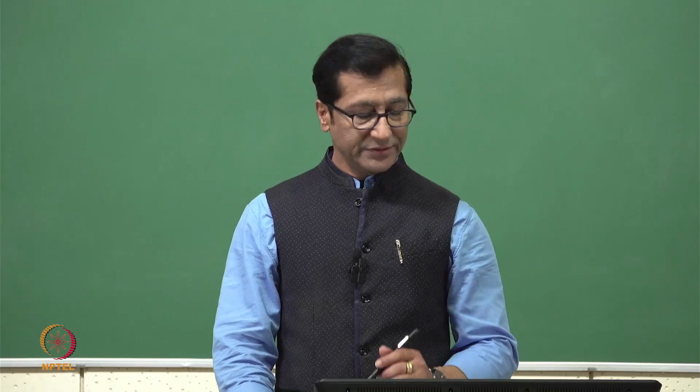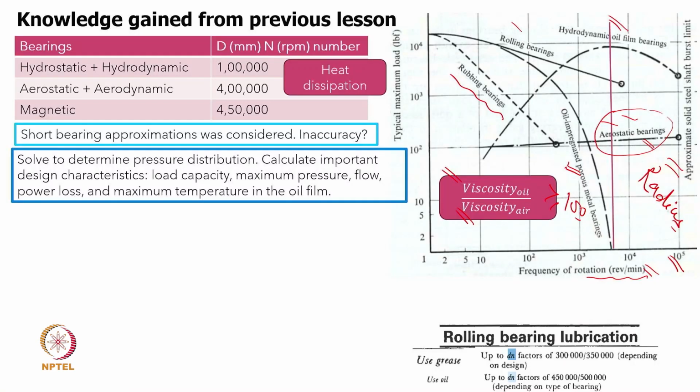Now, what has been learned from here is that many times a bearing is selected, and in this case particularly we have not defined a radius. So ideally we should use the term DN. DN is the diameter, that means the diameter of the shaft journal, times N, the RPM. So we consider the dimension and also the rotational speed, or basically velocity.